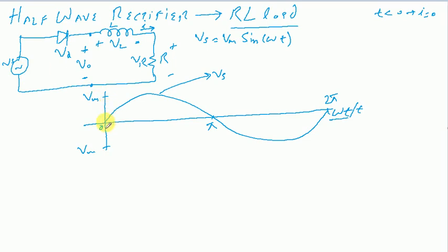At time t equal to 0, if we are considering an ideal diode, the diode which is connected between these 2 points will be replaced by effectively a short circuit, because an ideal diode will have 0 voltage drop across its terminals. At that time, we now need to consider the different waveforms, for example the output voltage and others, and how they look during that particular interval.